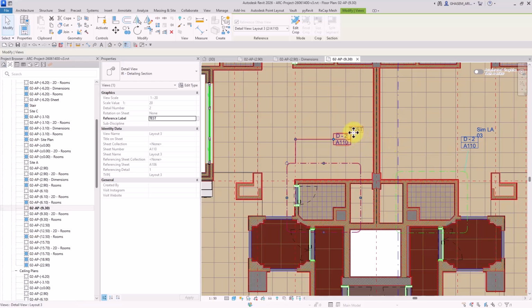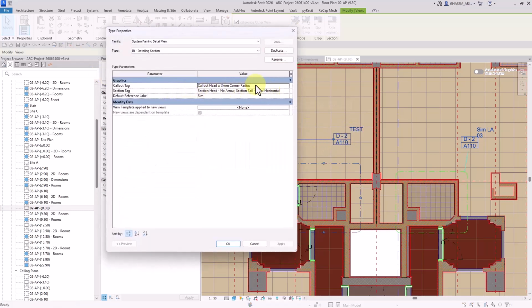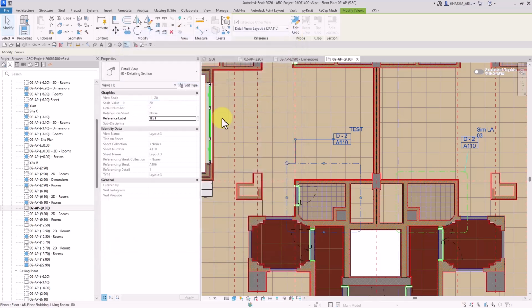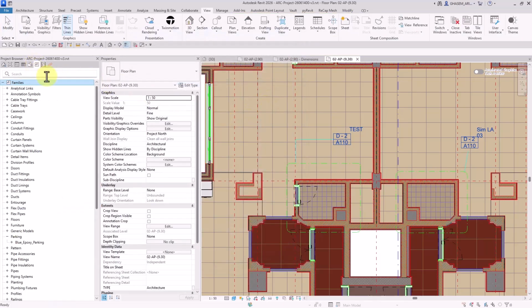Now, as I said, we have two interesting features. We talked about the first one, and number 2 is the ability to add shared parameters. But remember, guys, this ability would work only on four categories: callout heads, elevation marks, section marks, and view references. Now, let me elaborate on this. What's the name here? IR detail callout head. So I'm going to copy this, close these down, and search for it in the project browser.